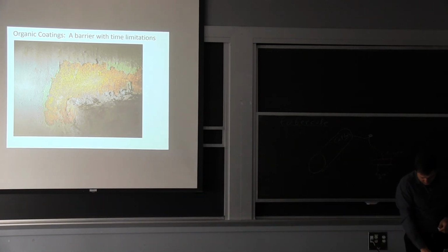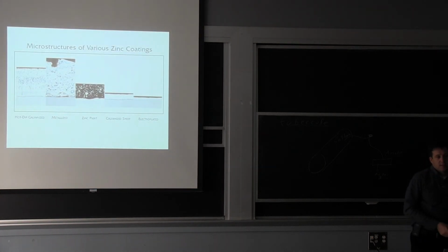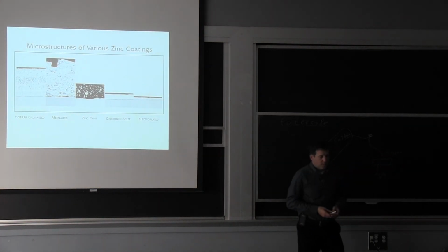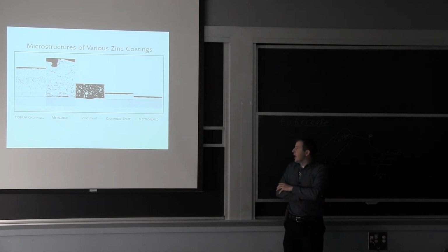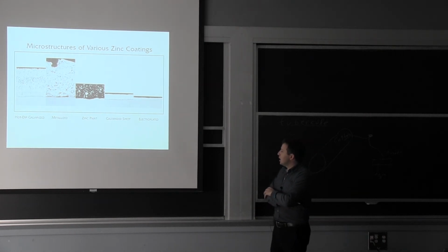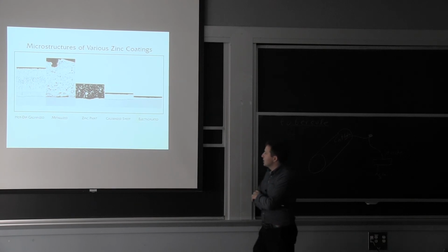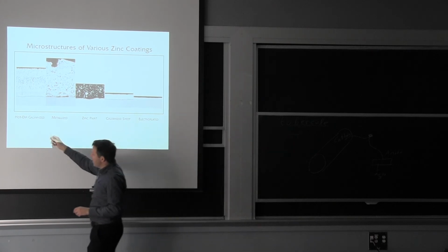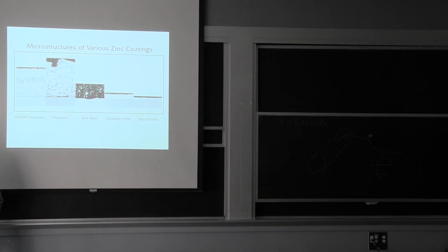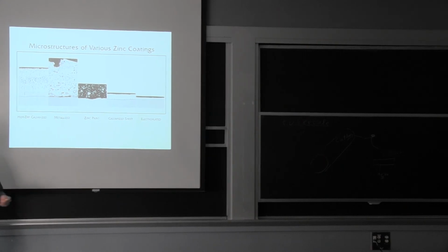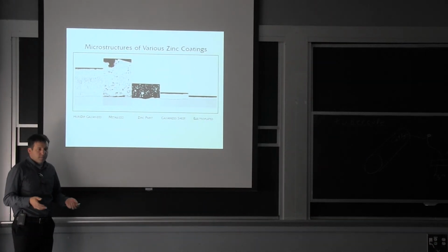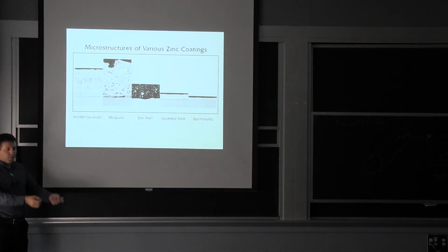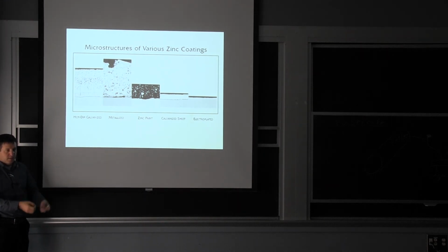So what we end up doing a lot of times is we galvanize the steel. It gives us a much greater life, and I don't want to go through all the details of galvanizing, but you see the different kinds here. So the hot dip galvanizing, I have some images for you, is really you take the steel. It can be rusty, right? When you make an assembly in a shop, it's very hard to have all very clean steel. So you take the steel, you put it in a bath to clean it with an acid, and then you literally dip it in liquid zinc.